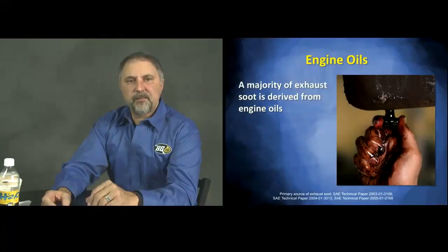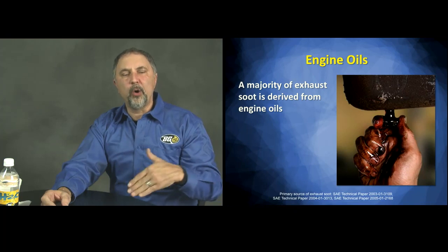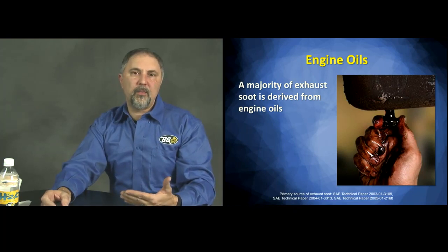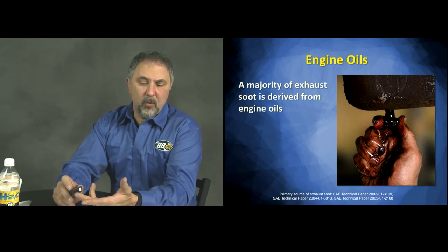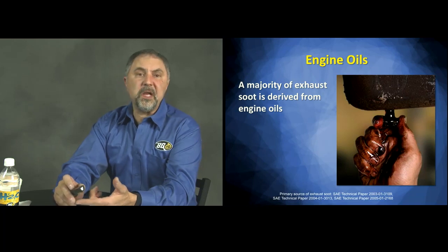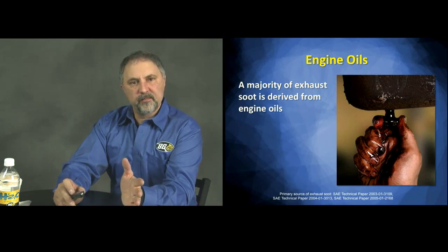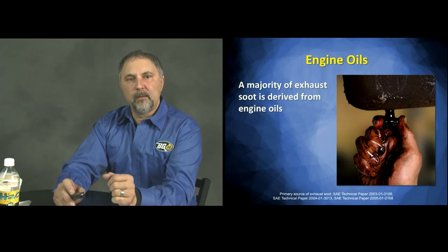So if I was going to ask you, what do you think the primary cause of soot is? This is your answer. And this isn't from me, or from our guys in the lab saying that oil is the primary contributor to soot. Most of the soot, whether you find it in the EGR or EGR coolers, or in the exhaust systems like the DOCs or the DPFs, or in the intake manifolds, wherever you find that soot, even on the turbos, backside, the turbine, that soot is primarily oil.